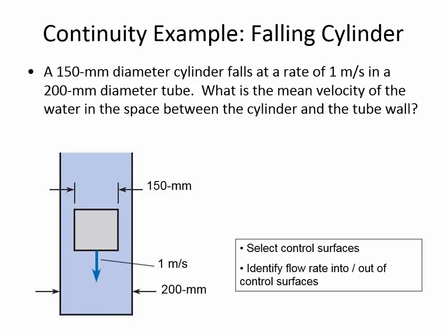And the way that we're going to be measuring force experimentally during the lab is we're going to put this lid on here, and we're going to use these weights of known mass. This brass weight is 100 grams, and so it's in equilibrium right now. There's a spring in here that's sort of holding everything up, and I'm going to make sure that this pointer points to the silver ring.